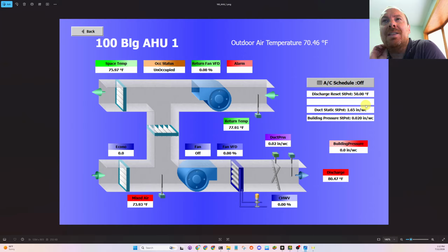And then it just looks odd that there's 50. So that's a red flag to me. Why does someone need 50-degree air? They're compensating for something in this old building that's not cooling properly.